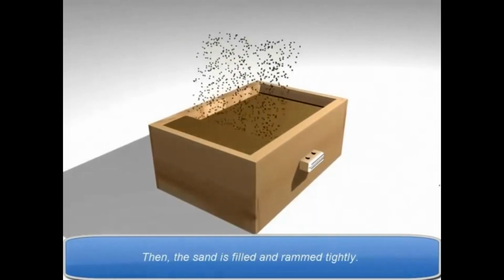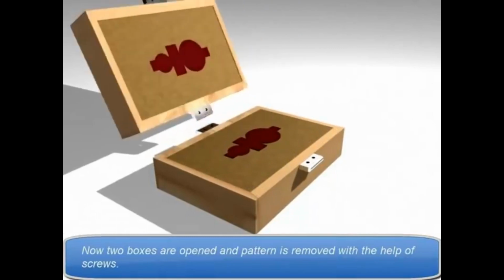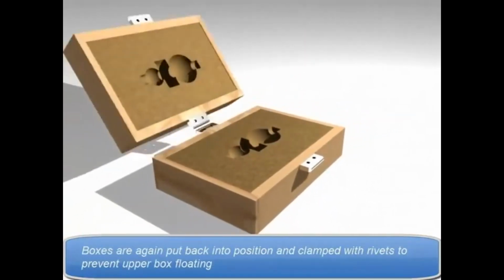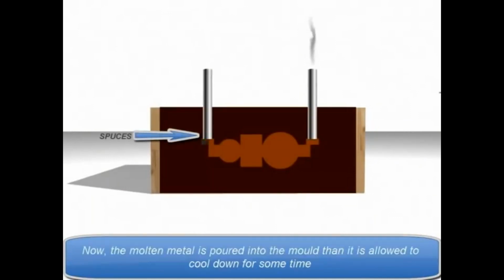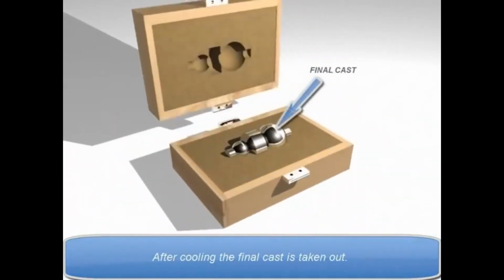Then the sand is filled and rammed tightly. Now the two boxes are opened and the pattern is removed with the help of screws. The boxes are again put back into position and clamped with rivets to prevent the upper box from floating. Gates and sprues are formed to pour the metal. Now the molten metal is poured into the mold. Then it is allowed to cool down for some time. After cooling, the final cast is taken out.